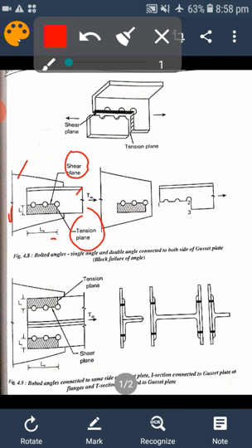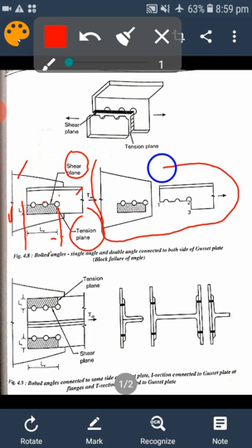Sorry, the length of the shear plane is measured from the edge of the member till the last bolt hole, from here to here, and this is called LV. LT is perpendicular to the load, from the center of the bolt hole to the toe of the section, which represents the length of the tension plane. They have also mentioned the failure mode here.